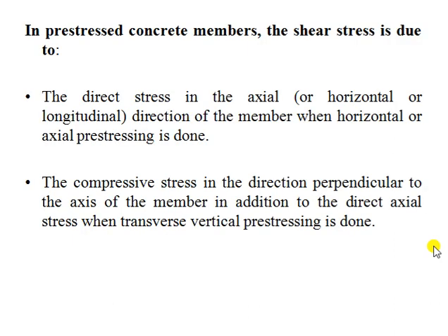When we consider a prestressed concrete member, the shear stresses distributed across the depth of the member are assumed to be linear and are a function of shear force and the properties of the cross section of the member. The effect of shear stress is to induce principal stresses on diagonal planes. The strength of concrete subjected to pure shear is nearly twice that in tension. Hence, local failure first appears in the form of a diagonal tension crack in regions of high shear stresses.